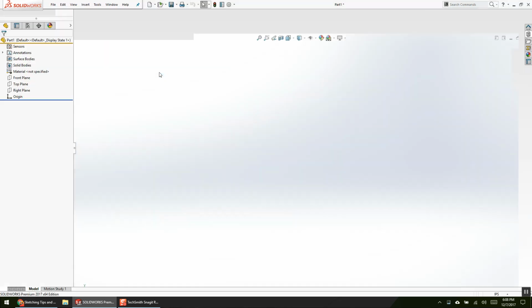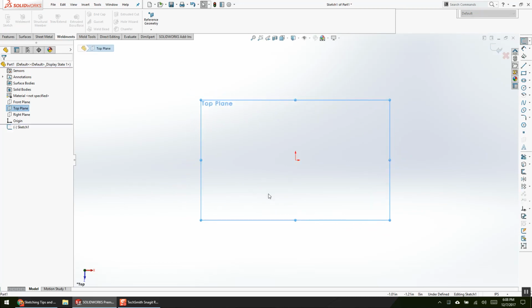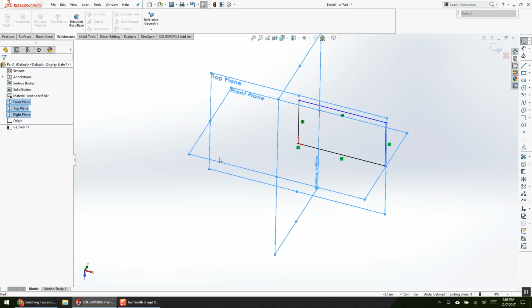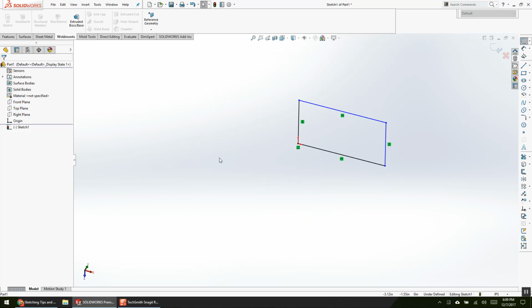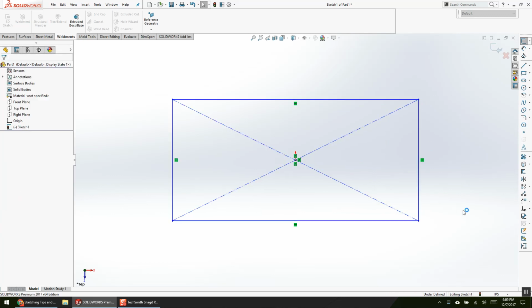The first thing that I often lecture about and talk on is your origin. If I'm going to draw this table that my laptop is sitting on, where should that origin be? Absolute middle, all the time, right? Because if I put the origin on the edge, it doesn't really bring me any value. My 3 planes are where? On the edge. So having an origin in the corner here with my 3 planes all in the corner isn't driving me any value. So there is a chance, and this is not guaranteed, but there is a chance that having the origin in the center will provide some value.